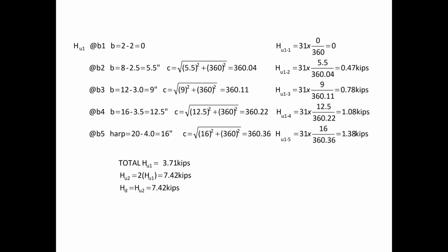And so that means that the actual vertical offset B for strand 3 is 9 inches. So on and so forth. So you just have to look at that section AA, look at the B that's given for the end of the bed, and then look at the section AA, and the difference between the strand location between those two is the actual vertical offset.